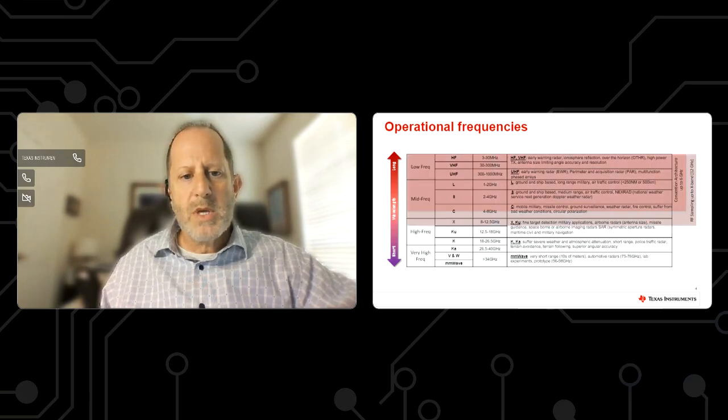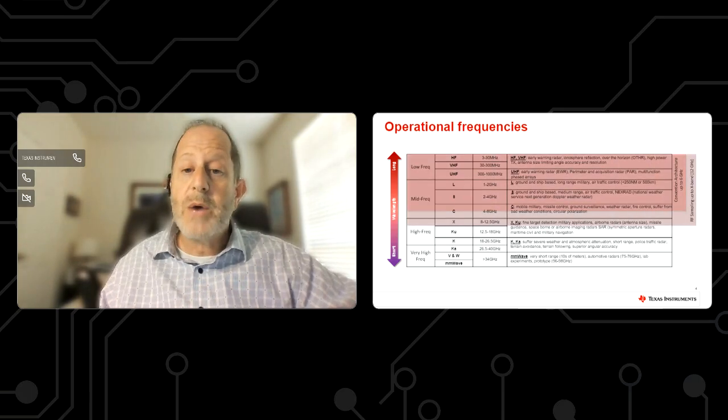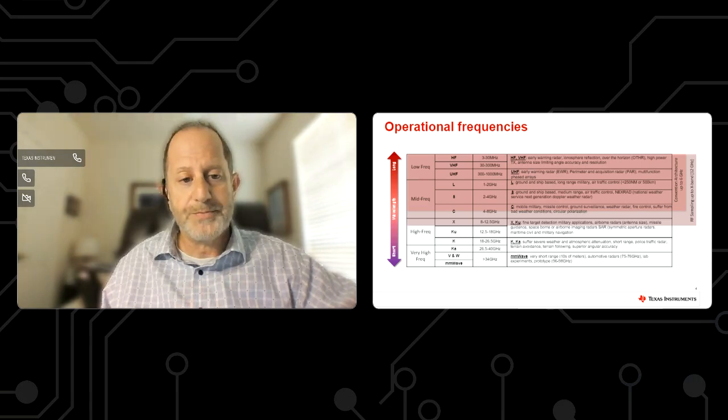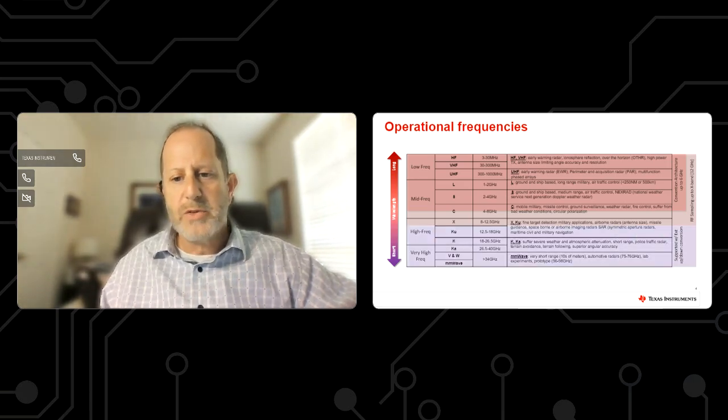If we push that out all the way up into X band, now we have some RF sampling architectures that can support all that low frequency stuff, the mid frequencies, and then go all the way up to 12 gigahertz. As we start to push higher into the K bands and beyond, now we need to do something a little bit different. RF sampling is not hitting these directly at this point, so adding some kind of external up and down conversion in order to hit these higher frequencies is the approach that we'll typically use.